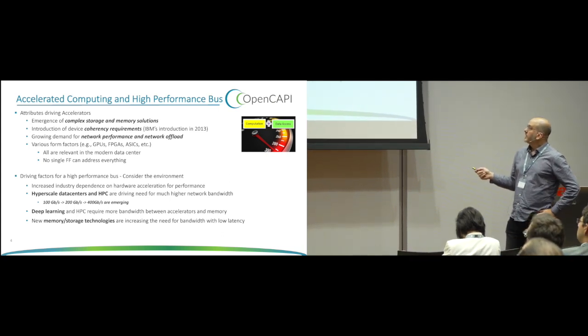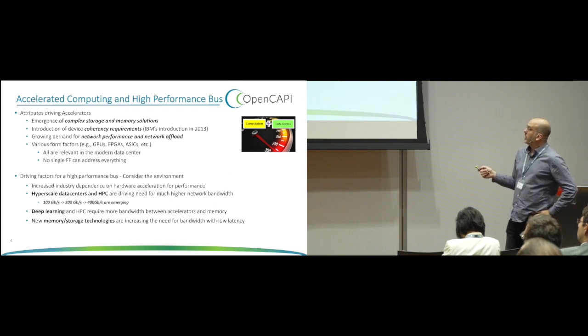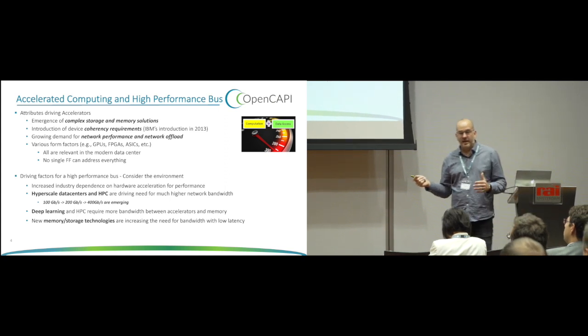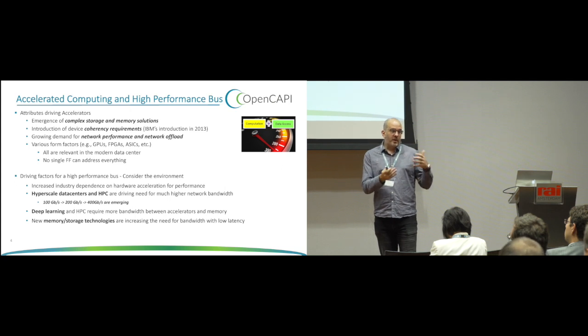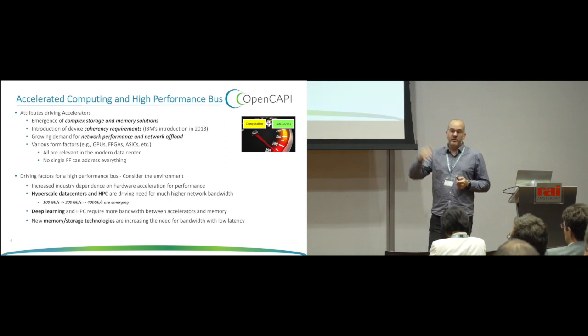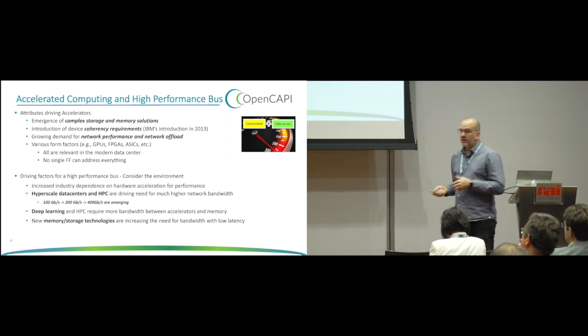We also have to be able to deal with network offload. That's what the last session in this room was about. And so we've got to do all these different things, right? There's nothing today that really lets us do that, especially in a hybrid way. If it's a memory and a storage device, it might need to do things that memory doesn't, like master commands. Maybe just to go tell the processor, hey, I've run out of decompressed memory, or I need some kind of maintenance on my structures. You can't really do that very efficiently across a DDR interface today.